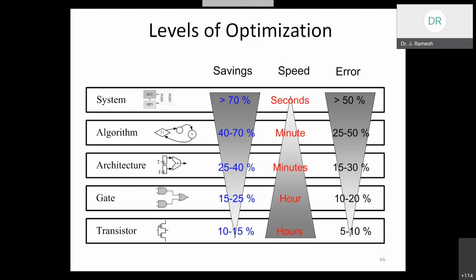Okay, and next to the system level, we have the architectural or behavioral level. There we can apply the concurrency increasing transformations. What type of concurrency? Concurrency in the sense that we are parallelizing things. Concurrency increasing transformations means we can go for the loop unrolling concept. In loop unrolling, we try to apply parallelism to the computation.